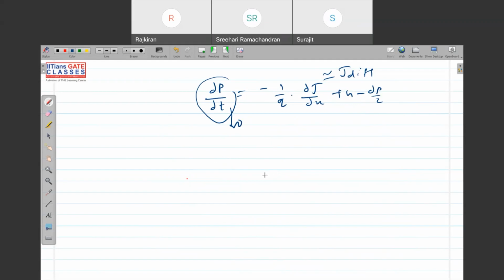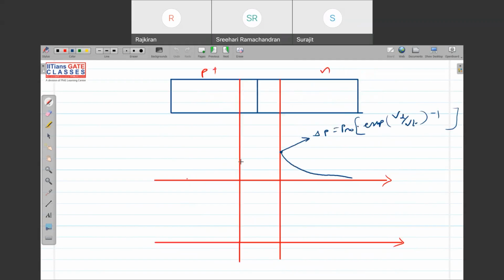So why is it 0, sir? Because I am in steady state. See, we are discussing the steady state condition. Okay, it is 0. There is no generation here. Because these have been injected from the P side to the N side, right? The holes have been injected from the P side to the N side. This is not generated, right?